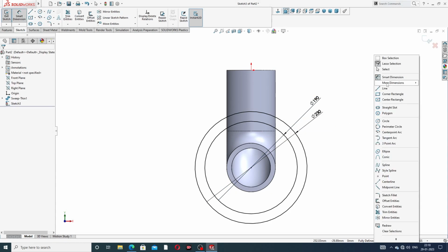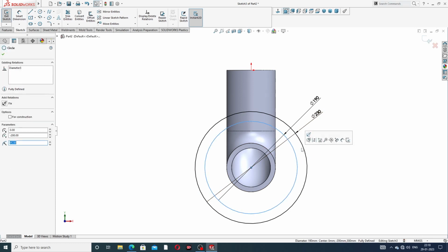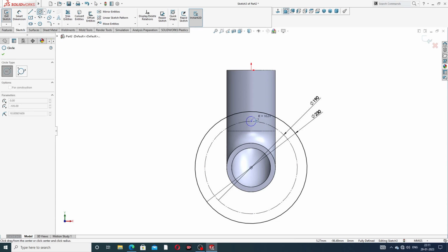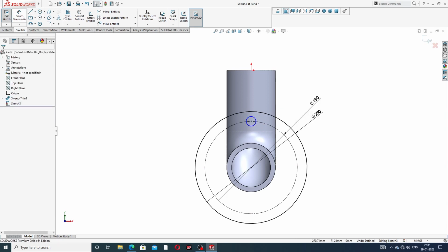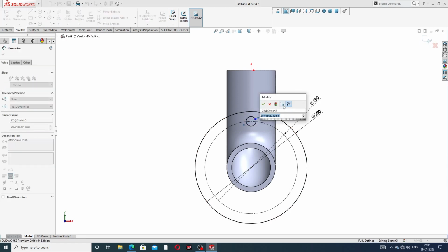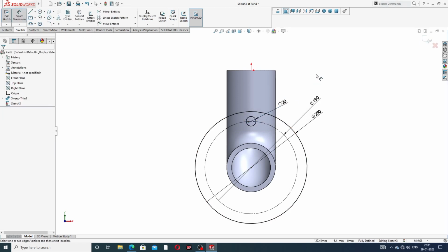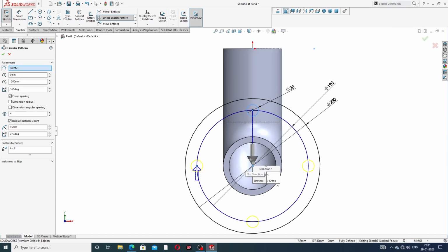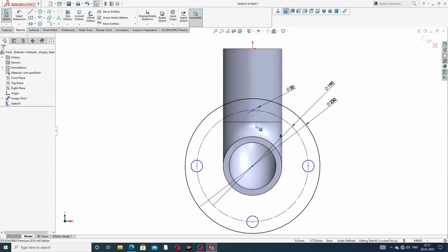Okay, but 190 millimeter is selected. This is a construction geometry. Some use point is discussed here, and this point is drawing a circle, and this diameter is 20 millimeter, correct. Again select a pattern. Pattern is circular pattern, and use this, and select a point. Point is this. Okay, all is perfect, and this is correct.